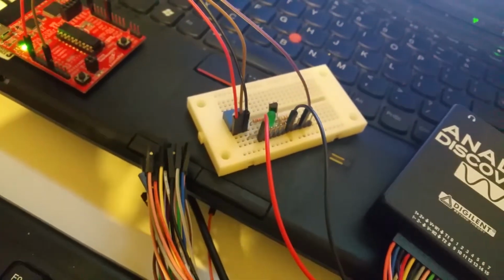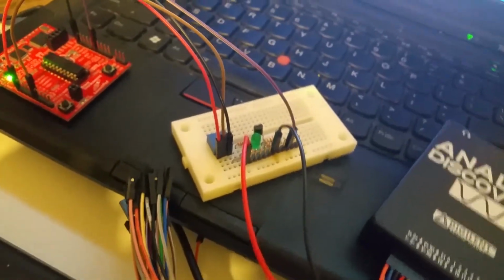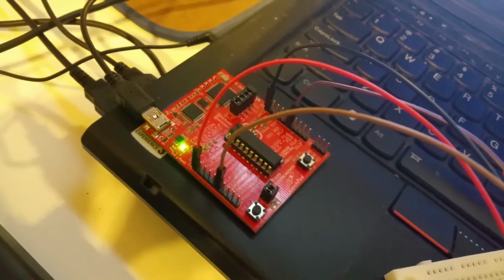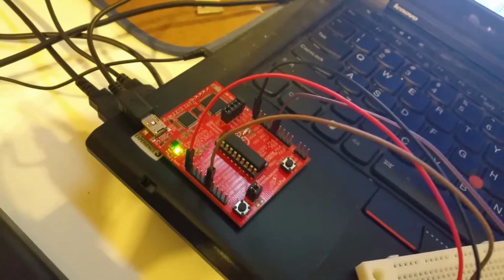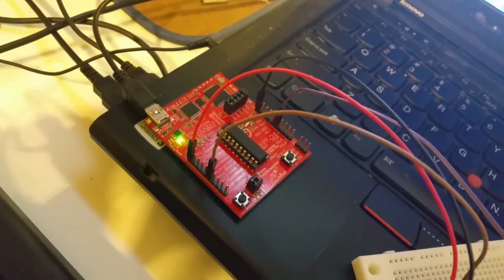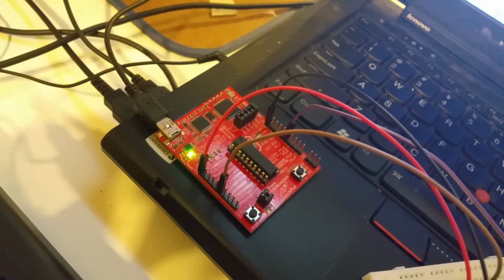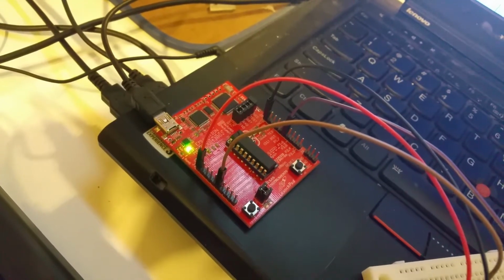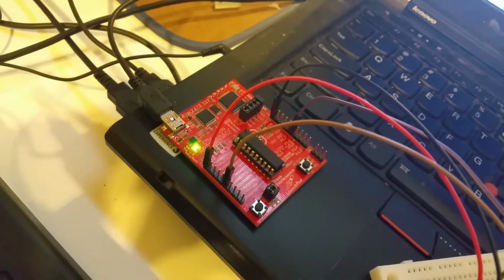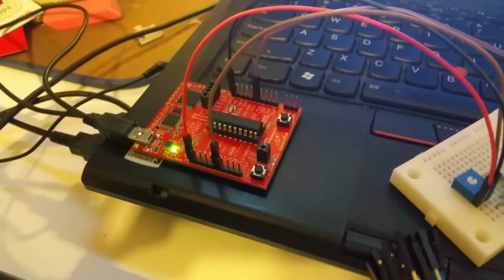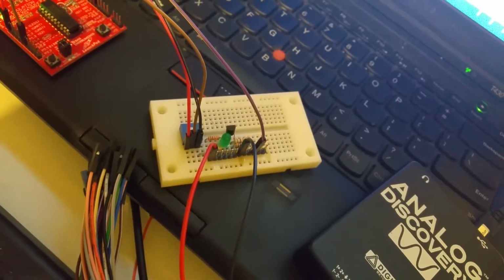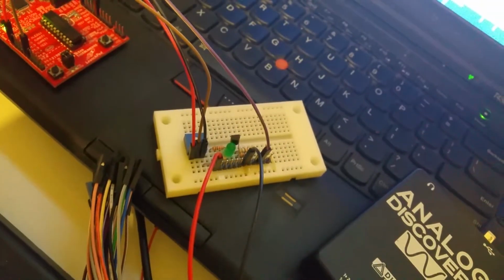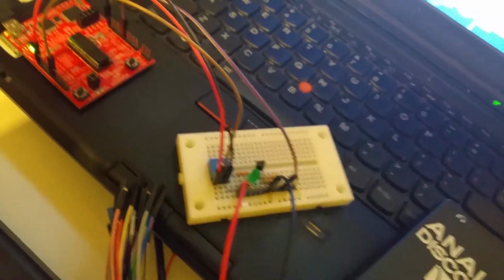I believe that the diode current at any pin for these MSP430s is limited to about 2 milliamps. I think you can get 6 milliamps without any significant consequences, but because the data sheet said 2 milliamps, I've made sure that I don't exceed that 2 milliamps. Alright.